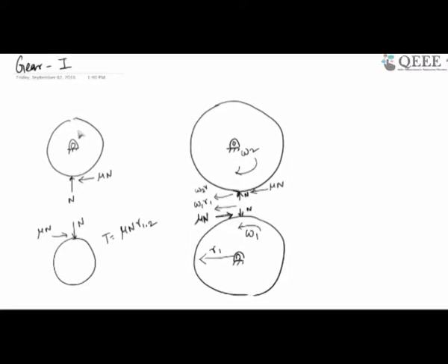So as you know, beams are very flexible structural elements, and this transverse force acting on a beam type of structure, which is the shaft in this case, will cause a shaft deflection. And once the shaft deflects, the gear which is sitting on the shaft will also move from its position, and either it will interfere or it will lose contact, the gear or the friction disc, as the case may be.